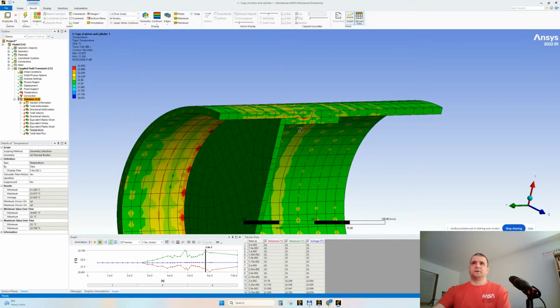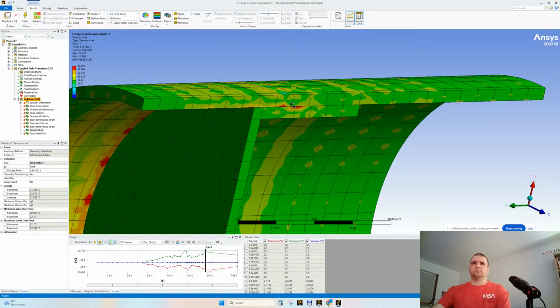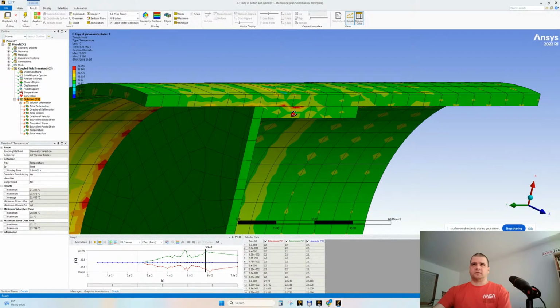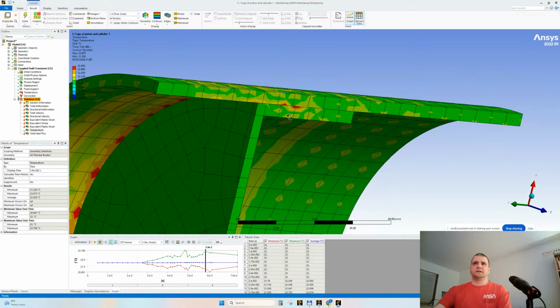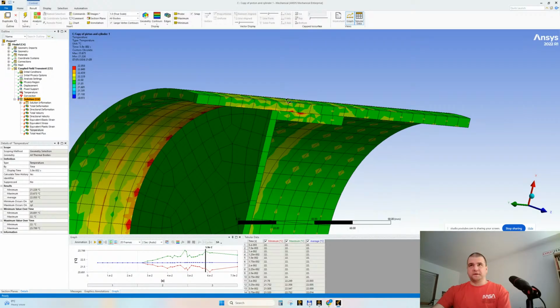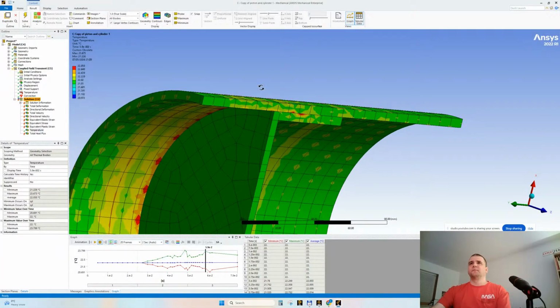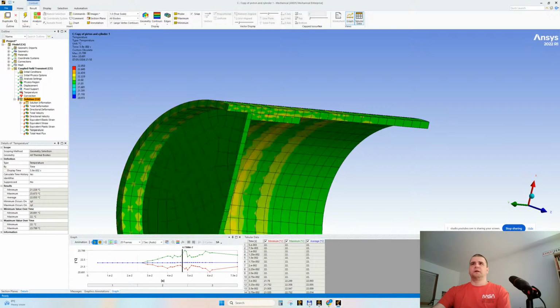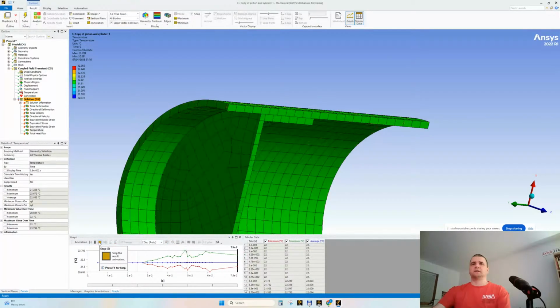And being the same diameter, they should dilate in tandem. A small problem is the fact that the gap is too small. This is why we have rings to take this into account, and this is why we have different materials in order to ensure different rates of dilation. In reality, we have materials with different thermal expansion coefficients. So normally, I think this is the problem with the different dilation.